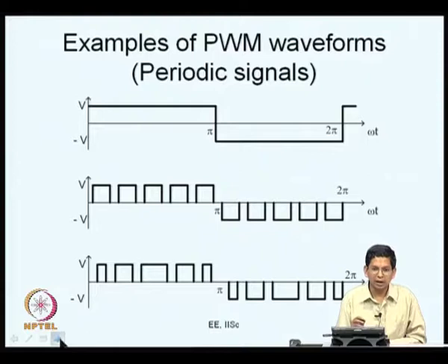How are you going to analyze the PWM waveform? That is one of the things. Here we are seeing some very simple PWM waveforms. The actual waveforms could be much more complicated, but such simple PWM waveforms are of great instructional value, and also in very high power converters you still have reasonably simple PWM waveforms because the switching frequencies are low in high power converters.